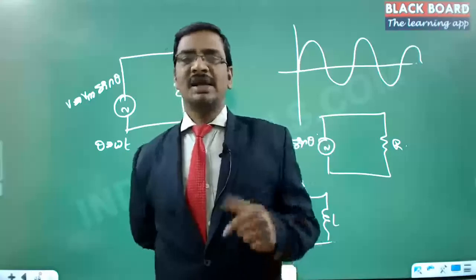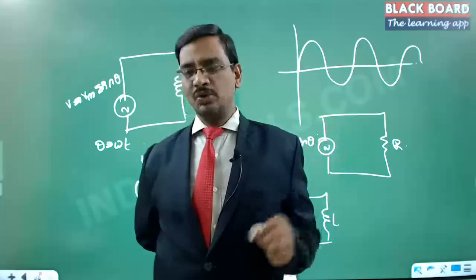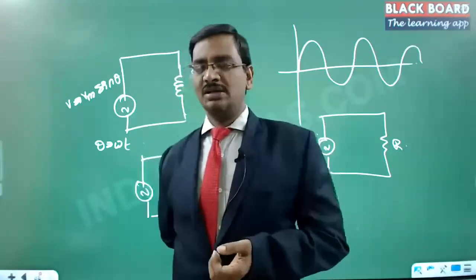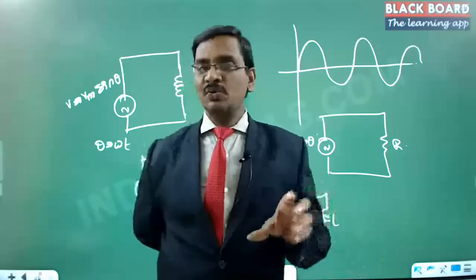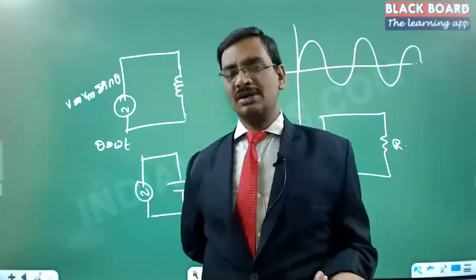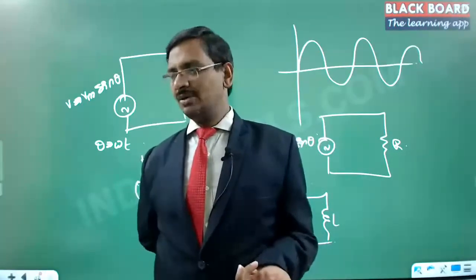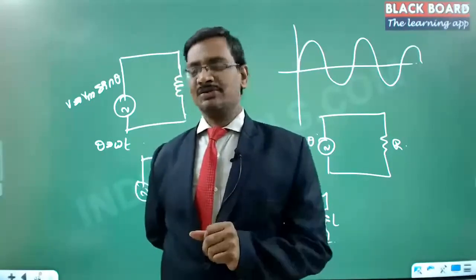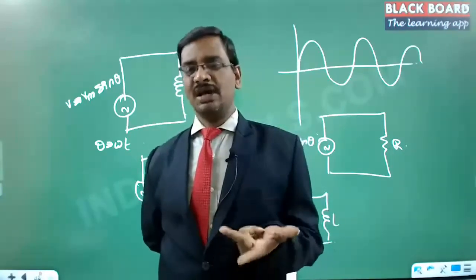And the second requirement is the RMS value. You wanted to calculate how much equivalent heat it can produce. The AC equivalent value for the DC is the RMS value which we have calculated. Now, exactly the power we have calculated in the normal way in case of DC. For AC, what can we do, because AC is continuously changing. Voltage is also changing and current is also changing. Then you have to calculate the product, and the product will be continuously changing, right? Obviously. Got it or not? The product is also continuously changing. Then you have to come up with a conclusion. So in the first case, we have taken the average value. In the second case, we have taken the RMS value.